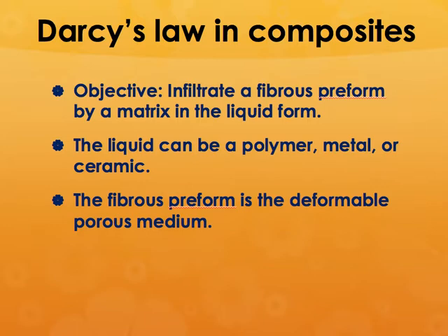And for resin transfer molding, or for any kind of infiltration of a resin through a fibrous preform, the law that governs that is called Darcy's law. It is mainly for composites, so you can define the time it takes for obtaining full infusion and what kind of viscosities are required and how much time is required, because all these things are going to control the final properties of your composite.